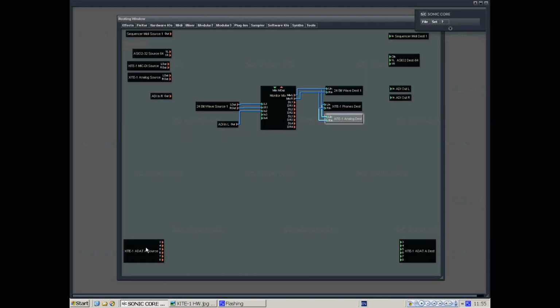You can also see the ins and outs of an ADAT connection. Observe that ADAT provides 8 channels, but here we have channels 1 and 2 missing. The reason is that I have used this ADAT to connect to a 2-channel external analog digital analog conversion unit, and I have renamed those 2 channels to my liking. These are the ins, these are the outs.